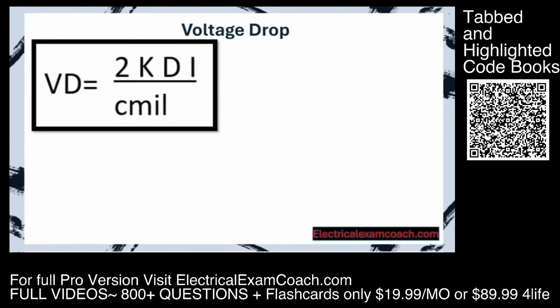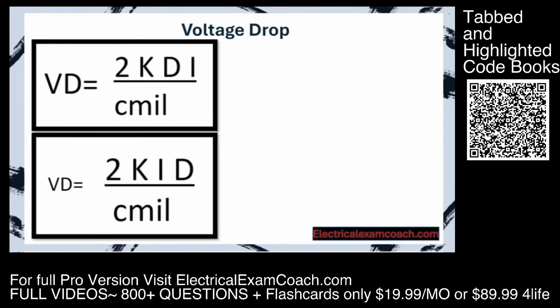If you were to do an internet search for a voltage drop formula, you would likely find this one right here. Voltage drop equals 2 K D I over C mil. And that is an excellent formula. And it's actually the one that I use. But I've rearranged it so it's easier to remember. I do it like this: 2 K I D over C mil. Easy to remember and easy to plug in.